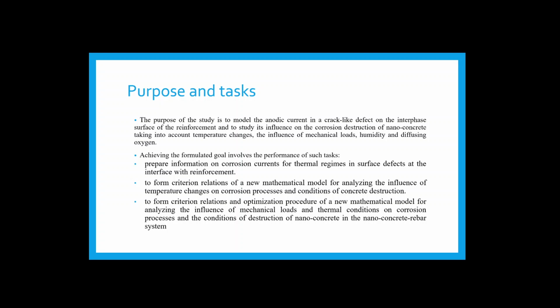The purpose and tasks. So the purpose of this study is to model the anodic current in a track-like defect on the interface surface on the reinforcement, and to study its influence on corrosion destruction of nanoconcrete, taking into account temperature changes, the influence of mechanical loads, humidity, and diffusing oxygen. To achieve this goal, there are several tasks.